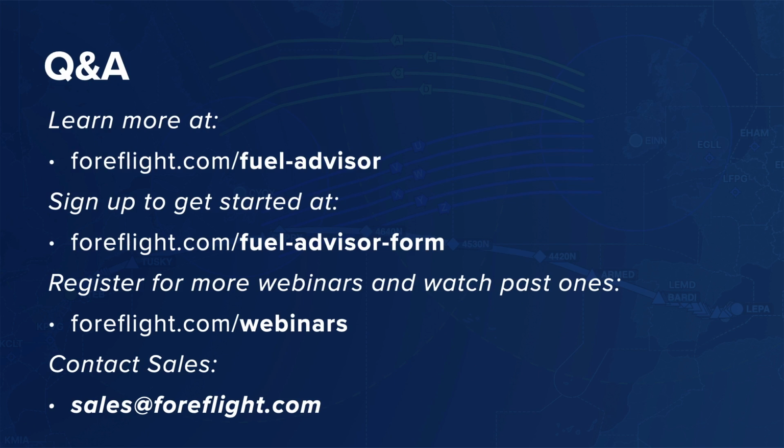Okay, next up. Does the tankering calculation take into account the threshold changes in fuel pricing, i.e. 500 to 1,000 gallons versus 1,001 to 1,500 gallons, and then utilize that in the algorithm? I can answer that one, Sam. Yes, it does. The tankering algorithm does take all the price breaks into account. Great, and I remember seeing that those price tiers are listed underneath each of the FBOs on the left in Fuel Advisor, so it even shows you directly what you can expect there.